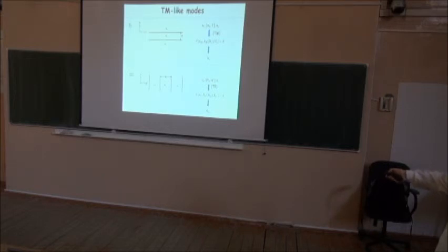Again, we saw from the BV diagram that we have a function that connects all those variables: the symmetry, the B number, and the V number there. We set that equal to 0, and we find our solution there, that is N2. So that's the new effective index for that structure.